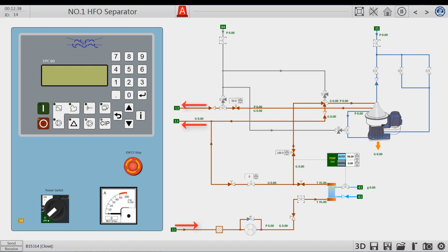Except for these 3 oil pipelines, there are also a compressed air line and a freshwater line. The compressed air provided by the compressed air pipeline is used to operate the relevant pneumatic valve parts. That is to say, here are some valves associated with the oil and water lines, which all need compressed air to control them.